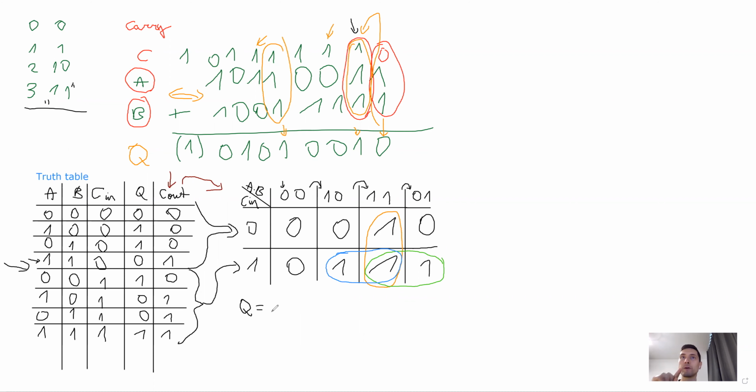and this unification works because of the following thing. If we have, sorry, I'll write like this, A times B times C plus A inverted times B times C, this A kind of cancels out because of the following thing. I can write it like this, equal to, I take B and C in front of the brackets, so B times C times, and in brackets A plus A inverted.